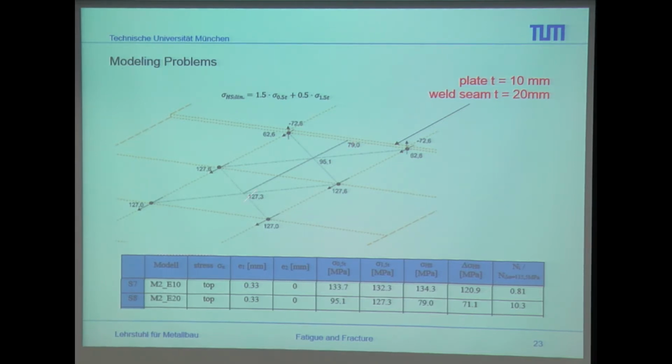If you go, for example, to numerical analysis, we have our information about our shell element. The shell element is always defined, for a simple definition, for a linear element, with 4 nodes. And the 4 nodes are not really evaluated on the element nodes, they are always evaluated on the Gauss points. These are the points of integration for our elements.